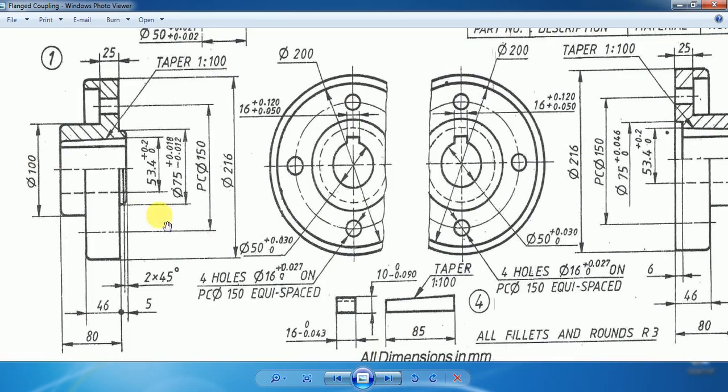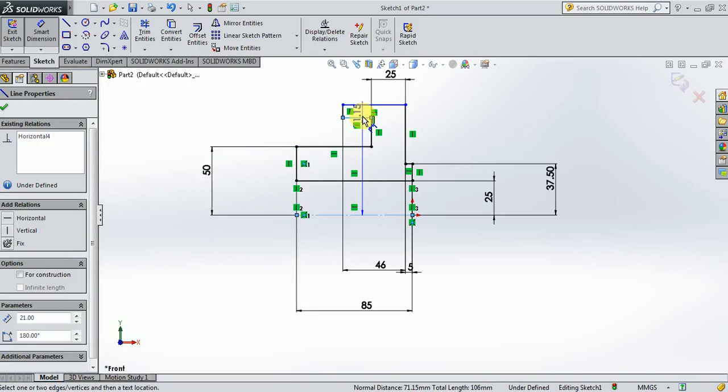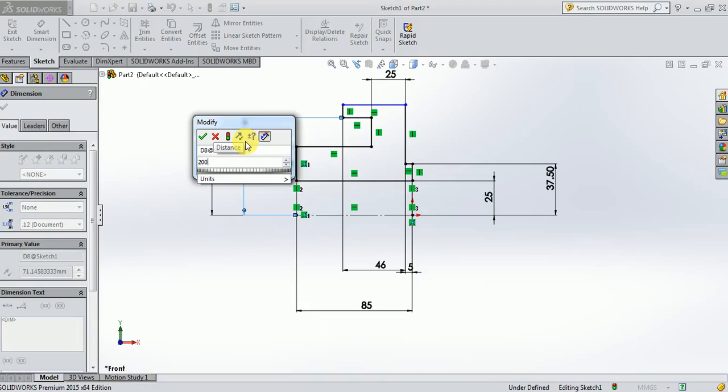Then what we need to do is give the diameter of the next highest diameter circle, that is this one. But this corresponds to the pitch circle diameter, the pitch circle on which 4 bolt holes are made, but it is not actually required right now. I will move on to this one now. This continuous circle, the second inner circle from the outside, has a diameter of 200 here. So therefore I am going to give the distance from this to this as 200 by 2.